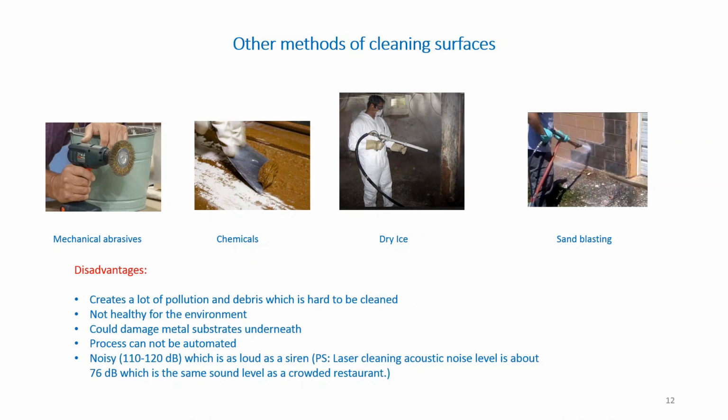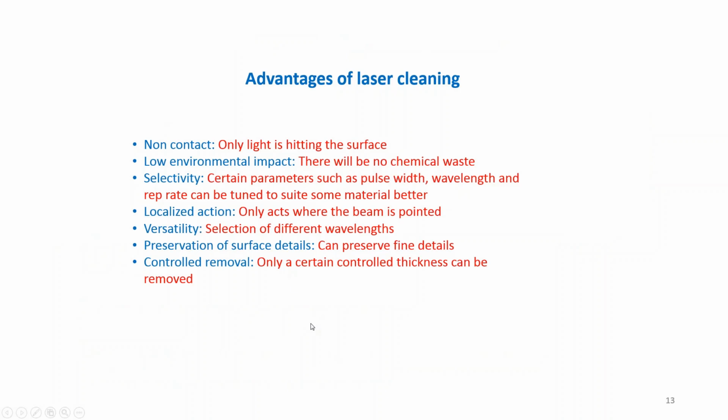The process usually needs an operator, cannot be automated, and it is pretty noisy, 110 to 120 decibels, which is as loud as a siren. Laser cleaning acoustic noise level is about 76 dB, which is the same sound level as a crowded restaurant. So compared to laser cleaning, dry ice and sandblasting are much more noisy.